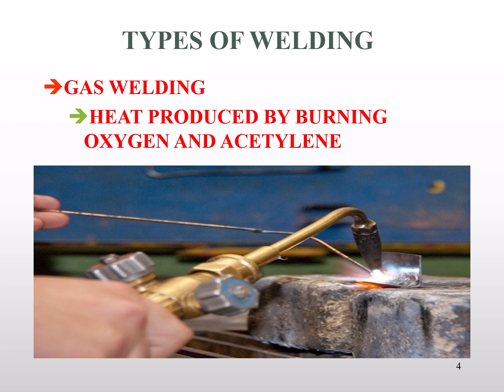It was the first method used to weld with because you needed no electricity. It is important to note, though, that without the addition of oxygen, acetylene will not burn at a temperature high enough to melt metal. So it takes those two gases combined. That's the reason you'll always have an oxygen involved with a fuel gas in gas welding, is to get the temperature high enough to actually weld.